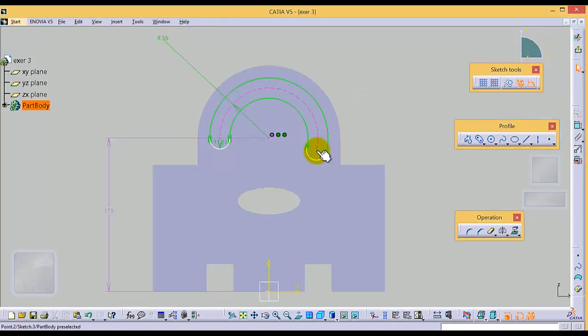And the dimension, so this dimension is basically over defining our sketch, so I am going to delete it. It automatically added 117, so I am going to delete it. Now as you see, these two points are not fixed. We needed to fix these two points,